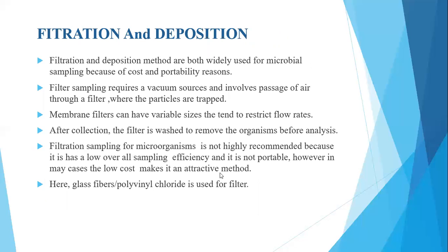The next and the last one will be filtration and deposition. Filtration and deposition methods are both widely used for microbial sampling because of cost and portability reasons. Filter sampling requires a vacuum source that involves the passage of air through the filter where the particles are trapped.